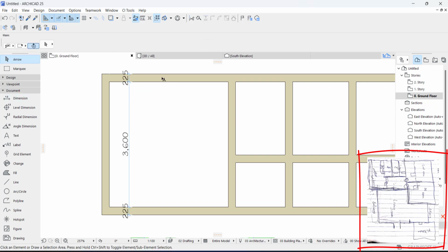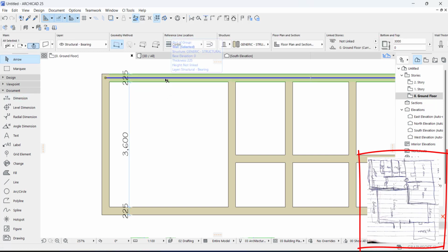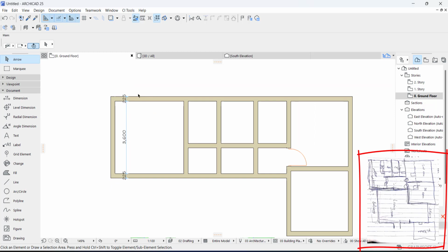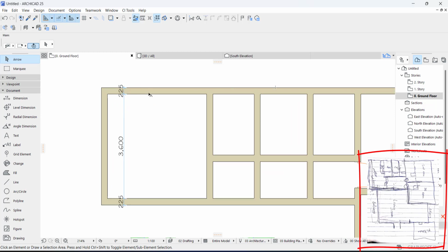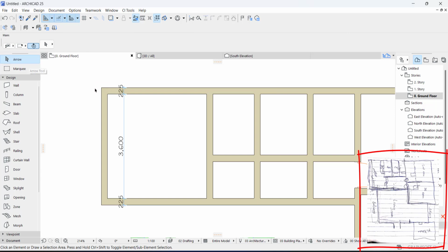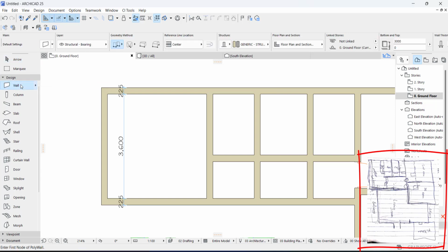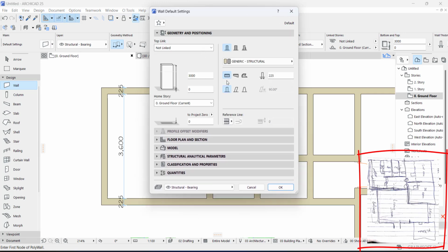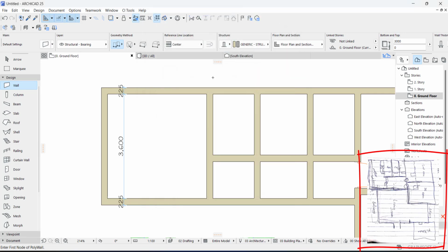The same thing with wall. When you have done your wall settings, right, you just pick the wall setting you have, to draw, so that you don't have to start setting your wall again. When you pick this wall, deselect whatever is going on now, you just press escape. Okay, everything will deselect. When you click this wall, it will be showing the settings we have done. That is because this is the last thing you picked.